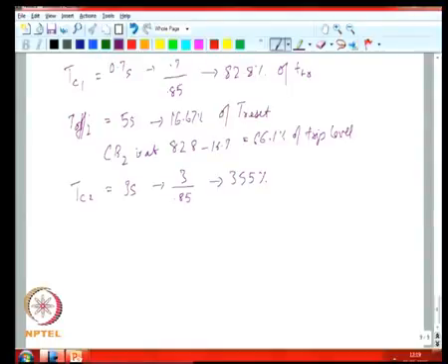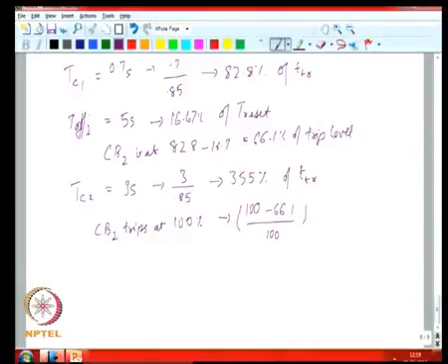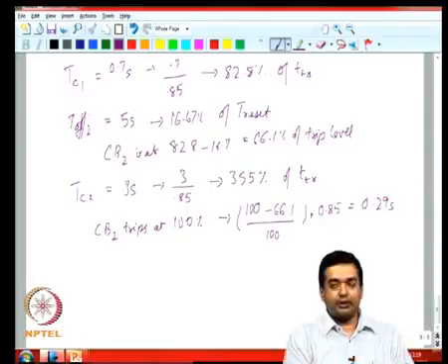So, your actual trip time for your circuit breaker corresponds to 100%. So, it did not require 3 seconds, it tripped in 0.3 seconds in the second reclose cycle.